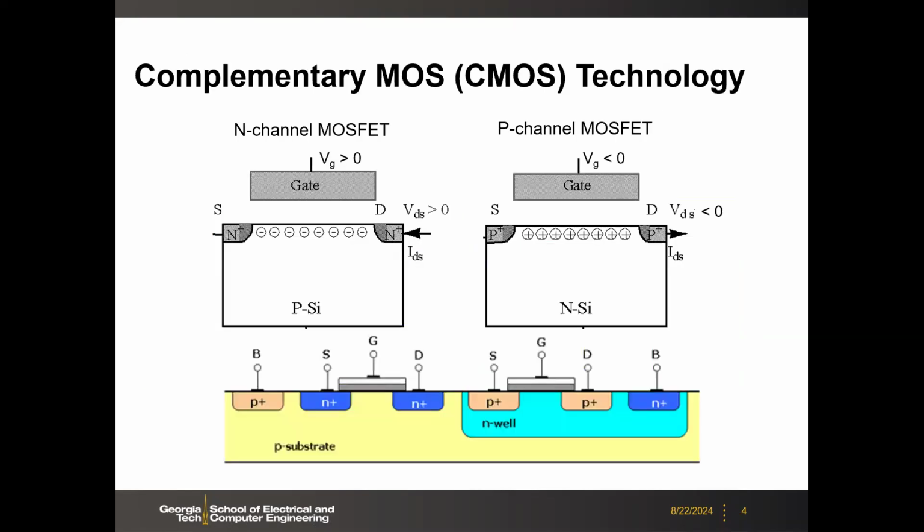And then the CMOS technology really requires NMOS and PMOS co-located, because for many of those Boolean logic operations, you need NMOS and PMOS, right? So here you can co-locate NMOS and PMOS, but for PMOS, you may need to pre-fabricate an N-well. So here, this forms the CMOS technology, right? The basic circuit, the inverter, is made of one NMOS and one PMOS.